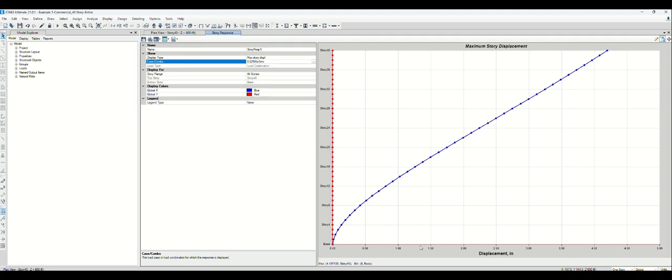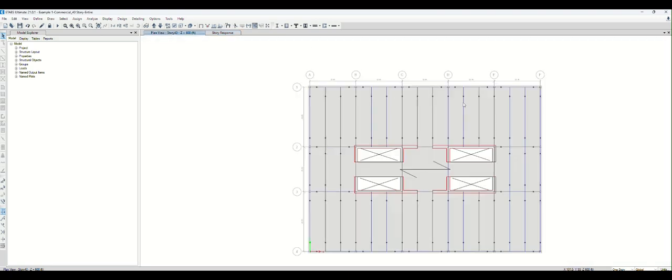So this is our deflection, which this model has a strong axis in X direction. Deflection under the wind X, service wind, I think we have a 4.19 inches deflection, but Y direction, let's check, 26 inches. So we have a lack of stiffness in Y direction. You can already see it. The building is rectangular, so the wind pressure on Y-axis is bigger because the tributary width is bigger than X, right?